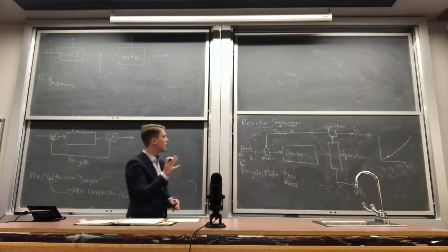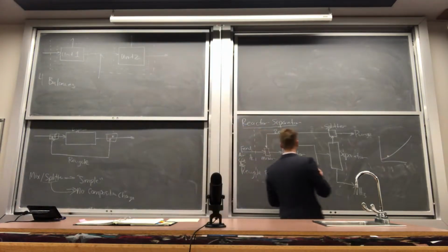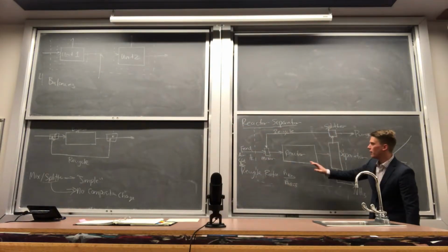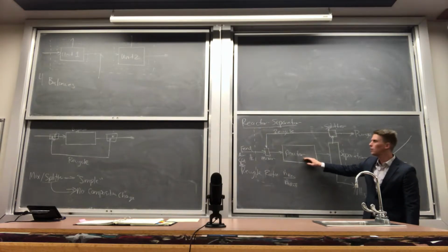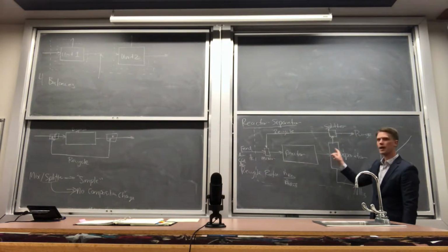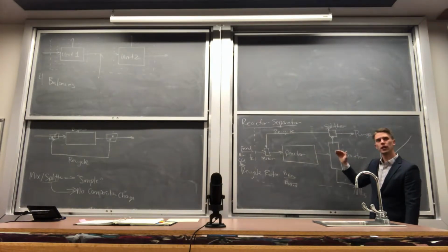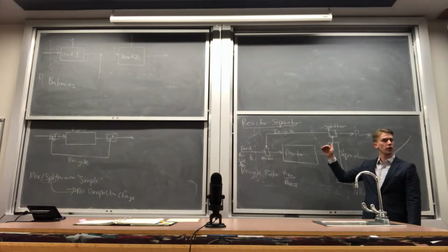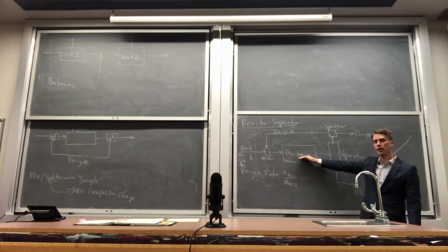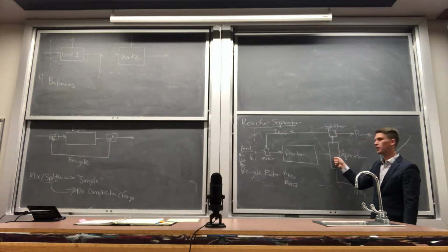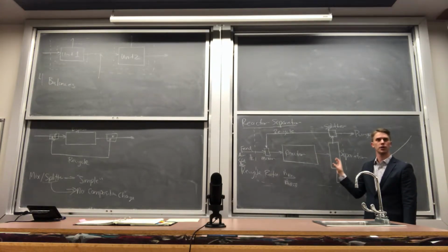But when you're in your senior design class, it's going to say, okay, should I have a bigger reactor to make sure that I have a greater recycle ratio and get a higher overall conversion? Is it worth going from a 90% overall conversion to a 95% overall conversion if it means my reactor has to be 4 times as big? Should I operate my separator at cryogenic temperatures? Should I operate it at ambient conditions? What kind of separator should I use? These are the design considerations that you'll be going over in your senior design class.